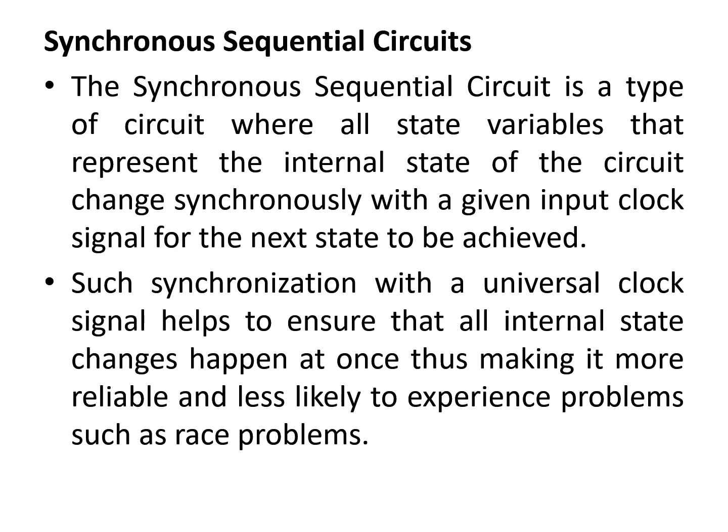Synchronous sequential circuits. The synchronous sequential circuit is a type of circuit where all state variables that represent the internal state of the circuit change synchronously with a given input clock signal for the next state to be achieved. Such synchronization with a universal clock signal helps to ensure that all internal state changes happen at once, thus making it more reliable and less likely to experience race problems.